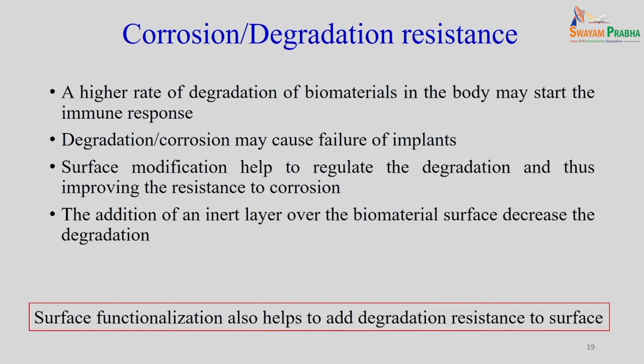And the last one, we will discuss the corrosion and degradation resistance. So, particularly if you are going for the bioresorbable materials, especially, let us say, magnesium alloys. So, for the magnesium alloys, they are bioresorbable or you can say biodegradable materials, but at the same time their rate of degradation should match the rate of tissue formation.